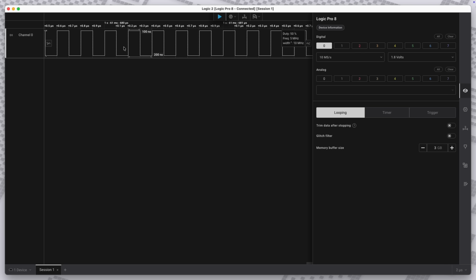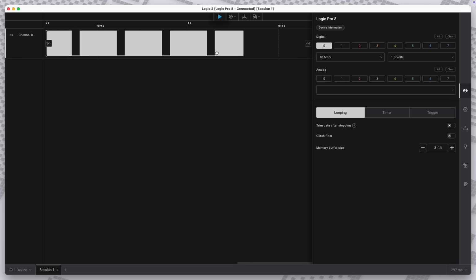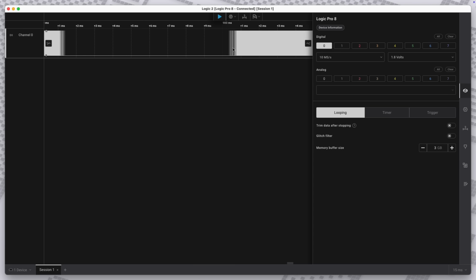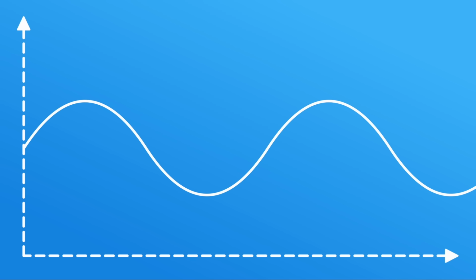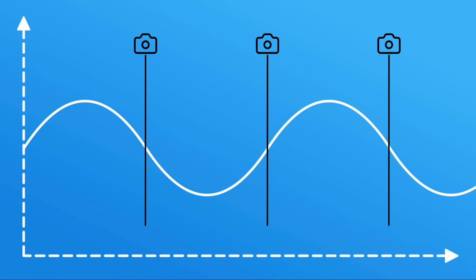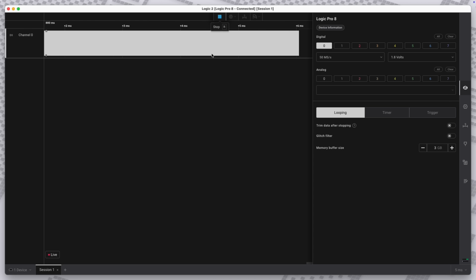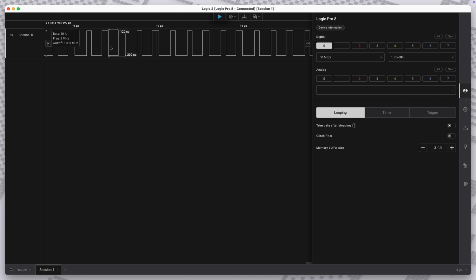It seems like every now and then we do not get a good capture. There's a gap. Here's what I think. The signal generator and logic analyzer are slowly moving out of phase. And at some point we're starting to sample exactly at the transitions. Then a bunch of readings will just be undefined garbage. We need 20 megasamples or more to start getting good readouts. And we're just looking at a stable clock. Chances are high we're still missing timing problems or glitches on a bus.